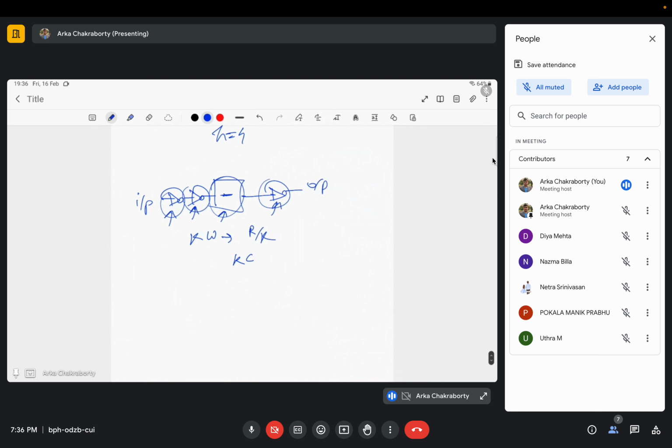Now, say I've been given a circuit, and there are some x number of terms which are not designed well, and I want to further improve the delay. What I do is insert a chain of buffers between them, so that the net scaling is in such a manner that all the parts do equal amount of work and I get the net delay as minimum.